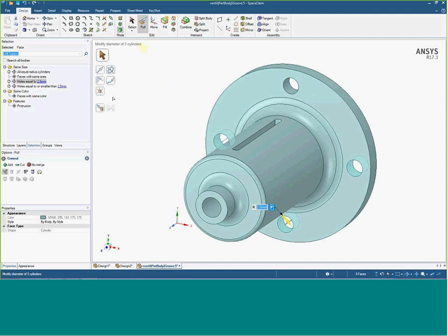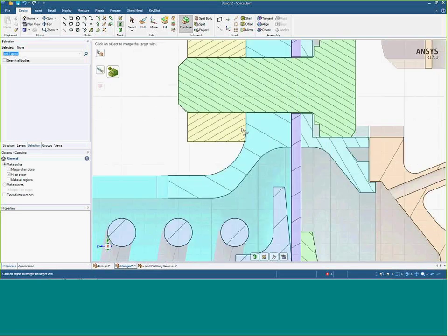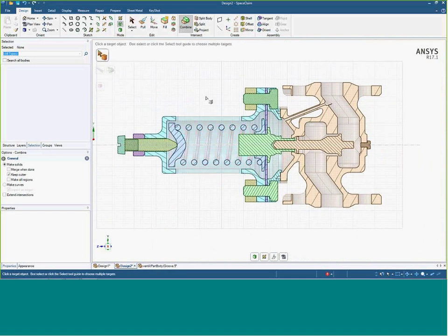And then we could use Pull up to, and just click the inside diameter in here, and it will pull all these holes up to that same radius. We can just double check that that worked. If I click this surface again with the power selection, it grabs all the equal radius cylinders, and now those are all the same. So that means back in our assembly, the other hole that was down here got updated. So you can do things like that.